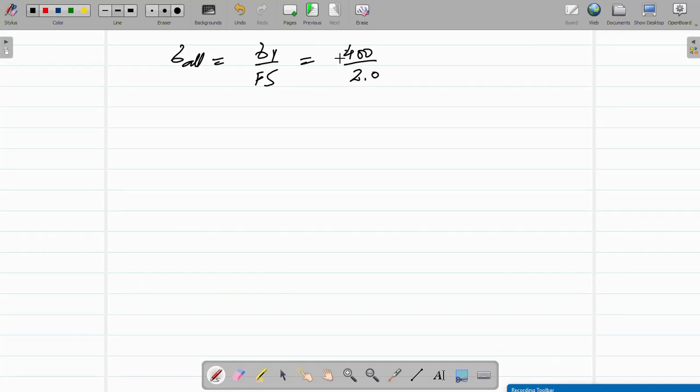I've told you that if human risk is involved, you can take up to 4, but human risk is not there, and there is dynamic load. Generally 1.25 to 2 is very reasonable, so you can take 1.5 or 1.8. I just take it as 2. So it's 200 megapascal. This is the allowable stress.